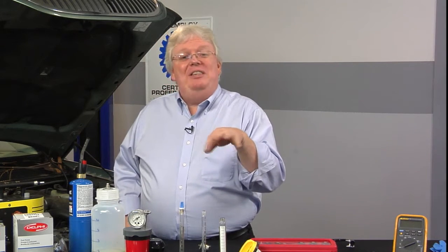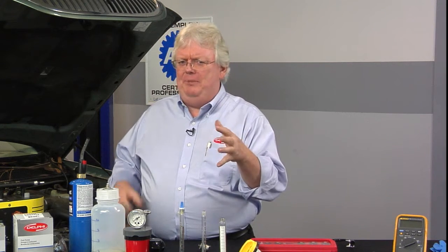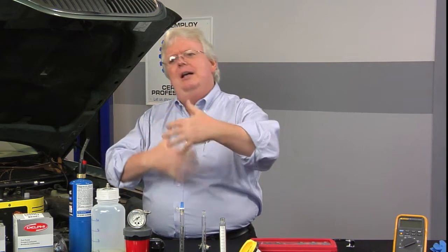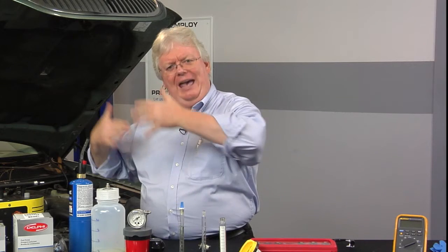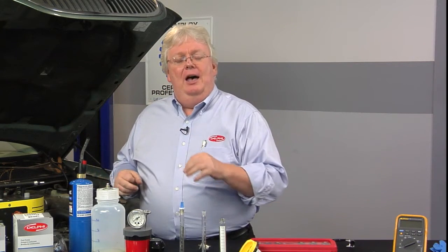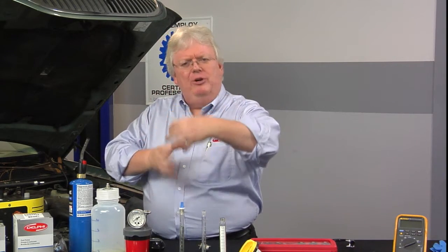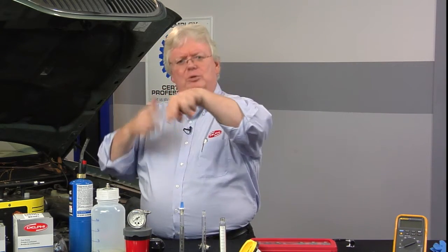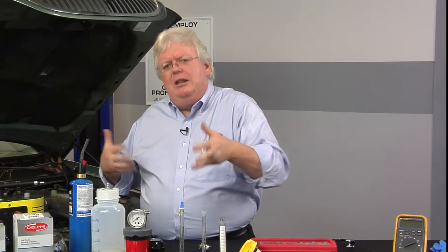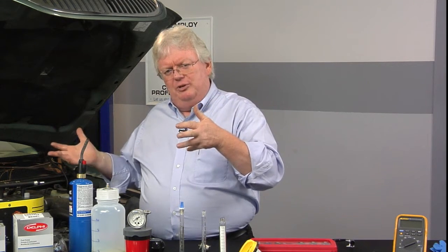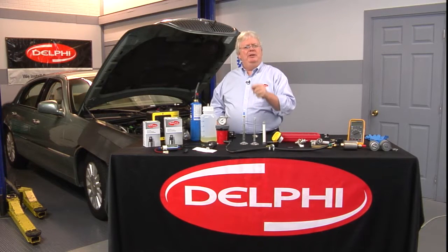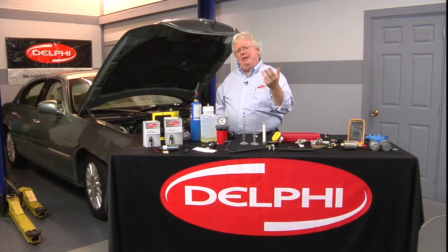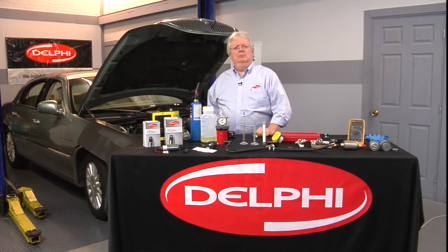Now, if it's not the same number, we may be looking at something like a second O2 sensor, a second catalytic converter, first and second cat, and so forth. So some pretty crazy stuff they do with newer vehicles, adding a pre and a pup converter and a secondary converter and O2 on each side. Those kind of things, we may be seeing multiple O2 sensors, so they are defining them in a little bit of a funky way. I'm not sure there, but go ahead and look. Next time you see that, Pete, if those two PIDs have the same value, it's the same thing.